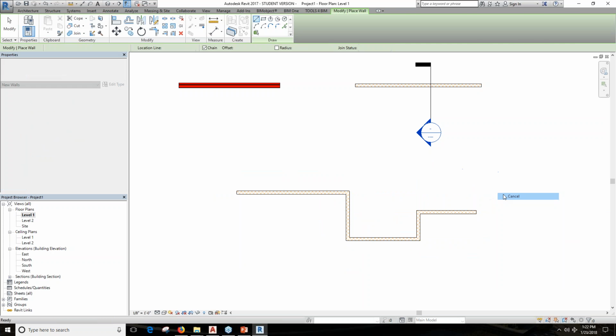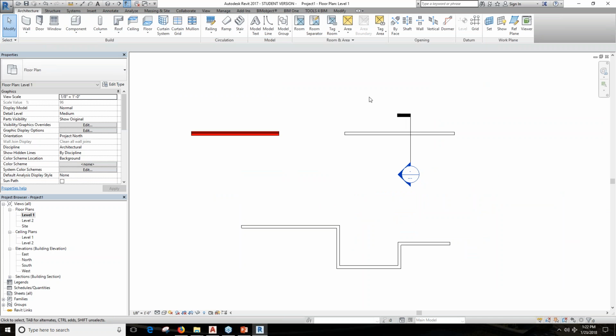and then look at the difference between this and the way that I did it before, without having to create any specific hatch or whatever. The beautiful thing about this is that this wall can be in a legend or in the schedules, and then automatically it is going to be identified as a fire rating wall that has this representation.